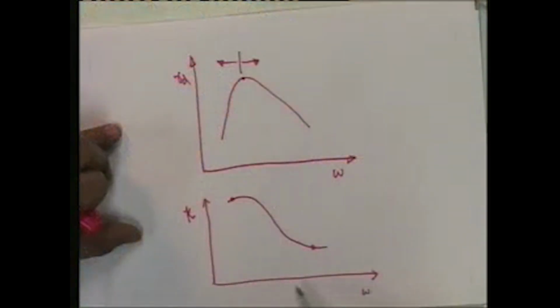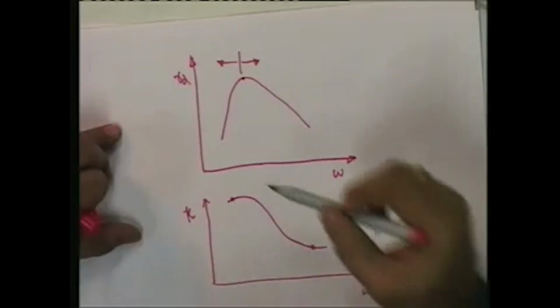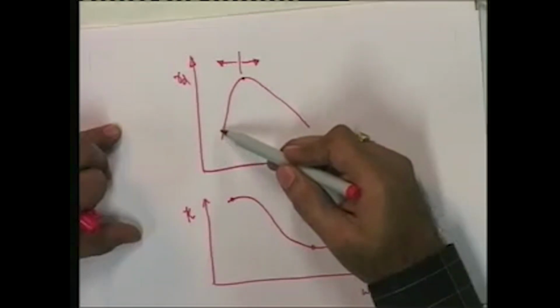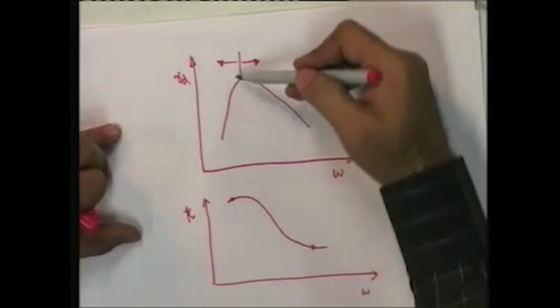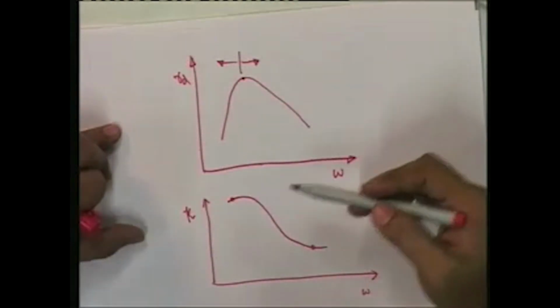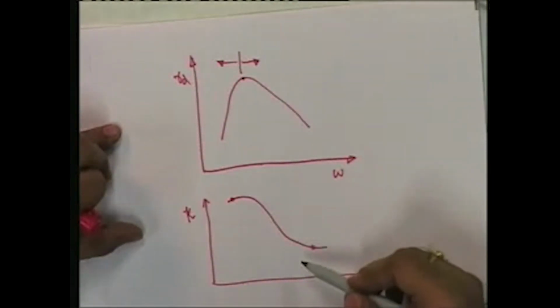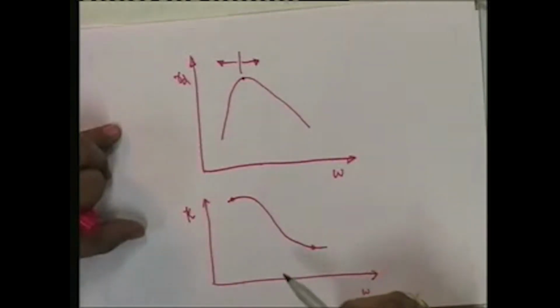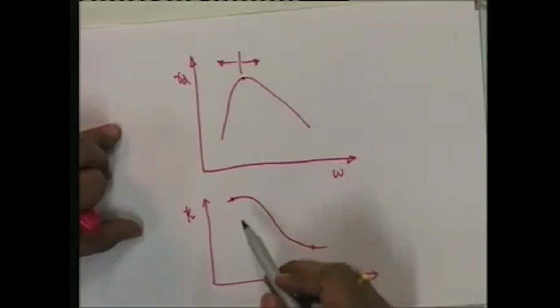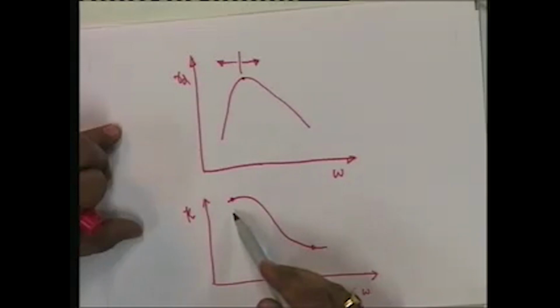So, what is happening is that as we increase the water content, for example in the compaction process, the orientation of the particles changes, that is the structure is gradually transforming from flocculent to a dispersed structure. As we increase the compactive effort, this also shows that on the dry side of optimum the permeability value will also be less with an increase in the compactive effort.